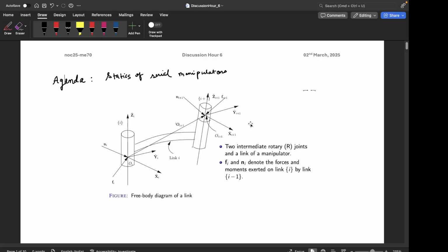Now, and then we finally discussed the velocity ellipsoids. So again, we saw that by taking the product of Jacobian transpose and the Jacobian, this special matrix and the eigenvalue and the eigenvector of this matrix basically tells us that in a given configuration, what is the direction in which the end effector can have the maximum velocity for a given angular rate or the joint velocities, and in which direction it has the minimum velocity.